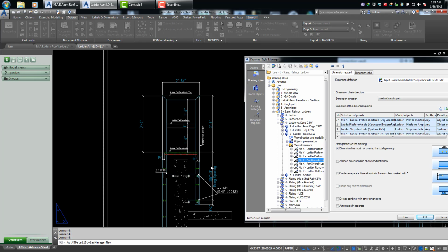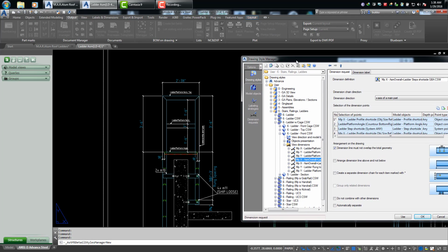So basically it gives you a running dimension which can be easily hooked with a measuring tape, so that the fabricator can lay these profiles out, and using your dimensions, he really doesn't have to think much, because anytime we start doing manual math in the shop, some guys are better at it than others, and some guys screw it up royally. So you've got to be careful about that, and you've got to try to provide them the best information you can, so that they don't have to really think that much as far as making manual calculations and things. So that's what I've done here.